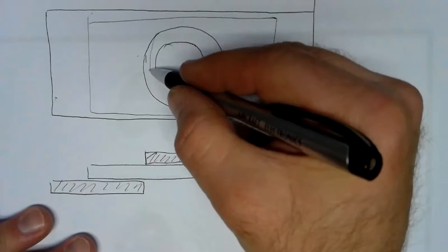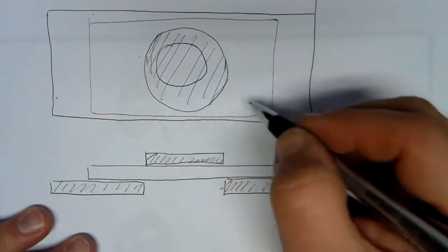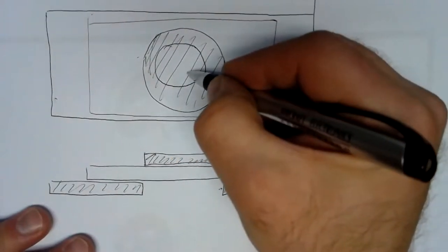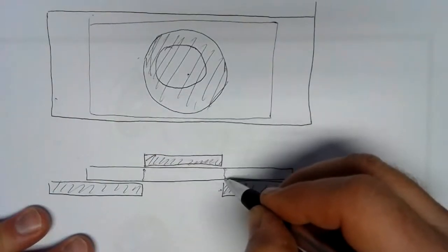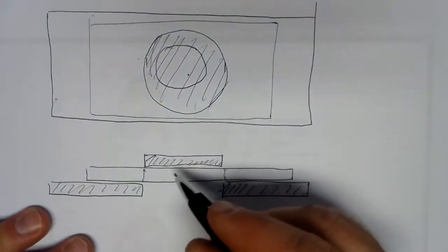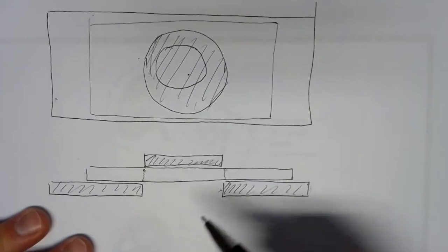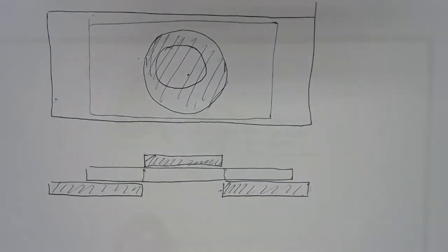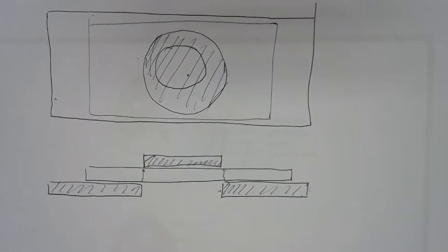And then we've got our die sitting right here. So the die would be pushed down and it would break through there in a circular shape. And it would leave a little slug of material that it punches out. And then there'd be a ring of broken material.